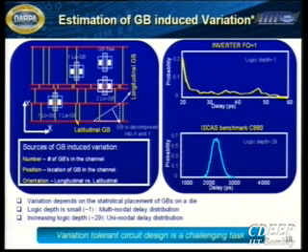The few things that one has to be careful about is repeatability. And so I'm going to be facing the problems. It's even more of a problem than what I had, for example, in my silicon technologies, right? Due to random dopant fluctuations, I have variations between transistors. Here, I have variations, and these are random variations due to the number of grain boundaries in the channel, position and location of the grain boundaries in the channel, right? Just like in the random dopant fluctuations, I have to worry about it.